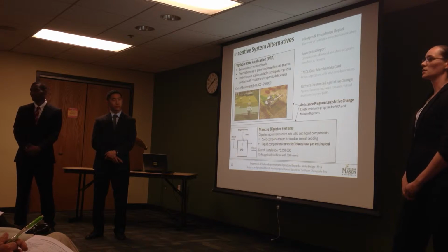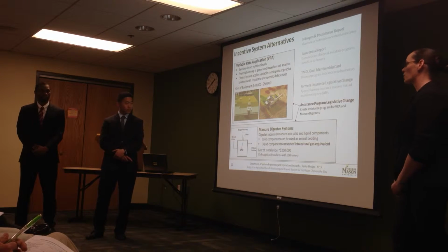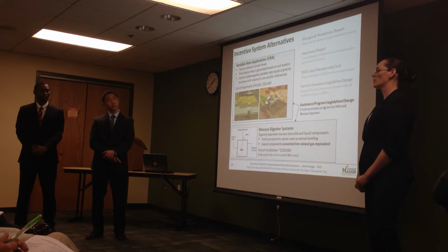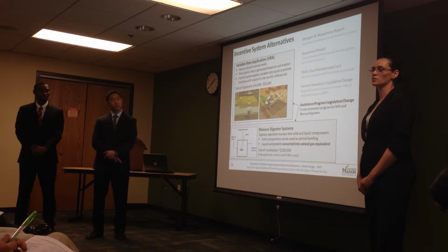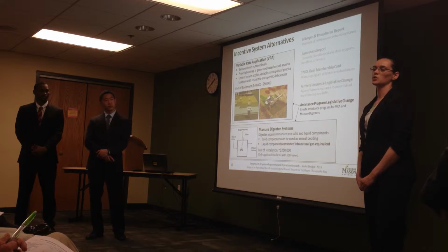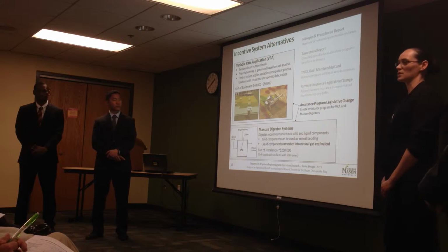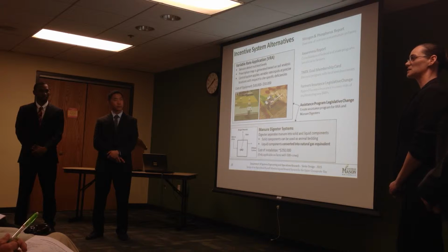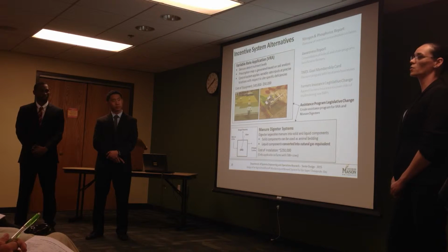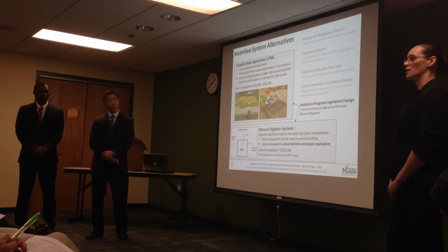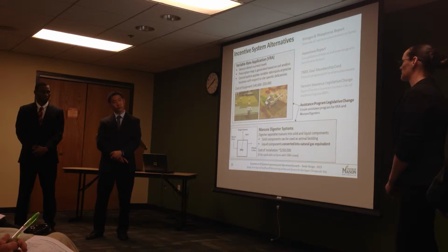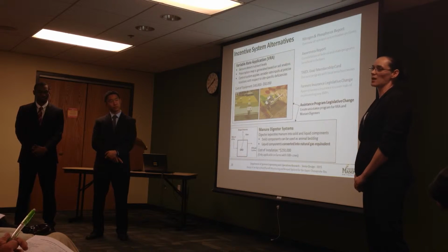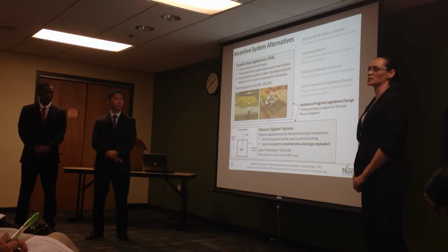The solid component can be used as an alternative form of animal bedding, while the liquid is converted into a natural gas equivalent. The benefit of this is that it provides a renewable energy source to the farmers. The cost of this system is expensive and starts at around $250,000 to $500,000. However, Cornell University has noted that there is an average payback period of about 5 years.